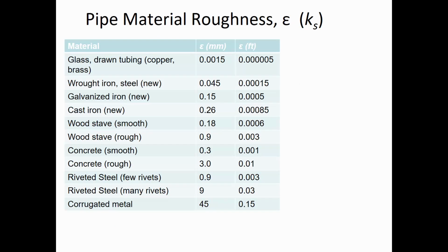Well, we've talked about how energy is lost partly as a function of how rough the pipe is. Water's flowing through a conduit, and at the edge of the flow boundary, where the water is in contact with the surface of the material, it's going to experience more friction if you have a really rough surface, let's say a rough concrete surface compared to a smooth glass surface.